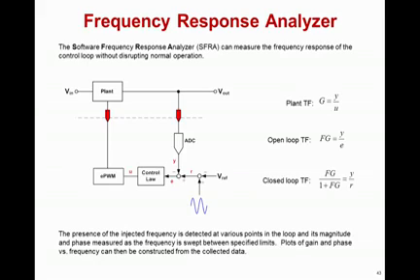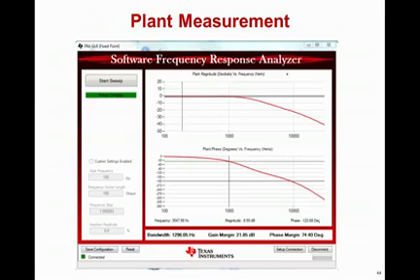The amplitude of this fixed function sine wave is then measured, and the phase of the plot can be determined. You iterate through and step through various frequencies on that sine wave to then create the Bode plots for both the gain and the phase plots of your Bode graph. As shown here, you can see that we would measure, in this case, the plant and plot those points accordingly.